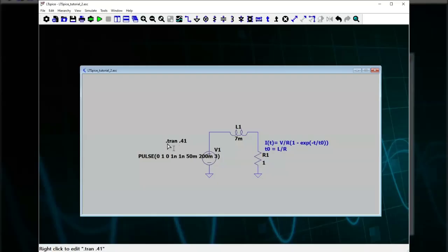This is a SPICE directive, and after you select the things that we just talked about, you need to paste this into your schematic with your left mouse button. Now this comes from configuration of the source. So you right click on the source, and in the dialog box you're going to see 1, 2, 3, 4, 5, 6, 7, 8 things that you can fill out. And then after you do that, this right here will be populated.